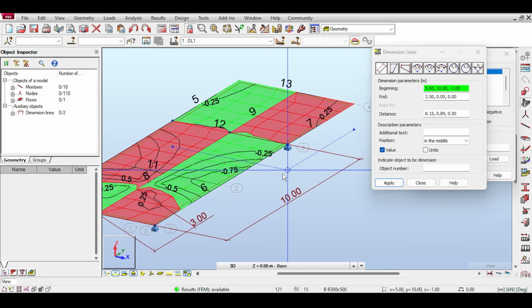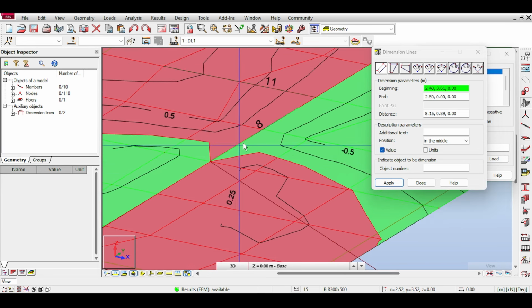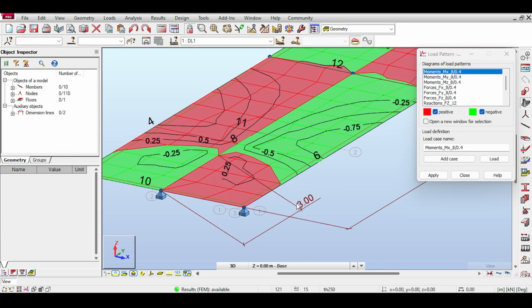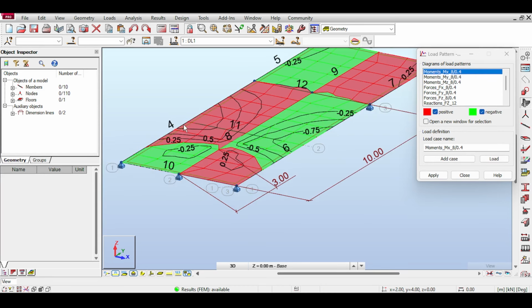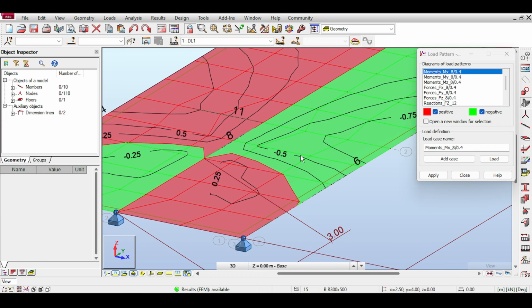Yeah, so it's around 0.4, not perfectly 0.4. The reason it's around 0.4 is that, due to the finite element mesh, that's the closest it can get to. It's not perfect, but it's something, I suppose. So this is the torsional influence surface of the torsion at this point. These are given in contour maps.